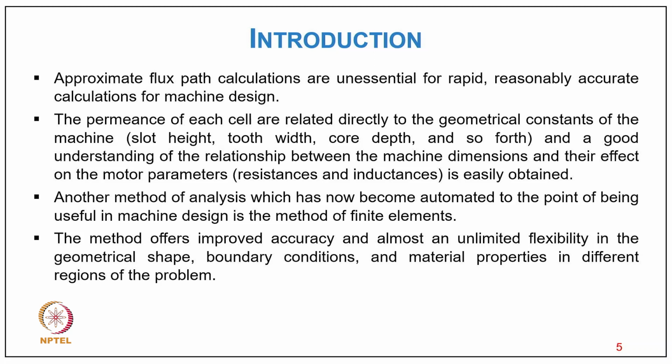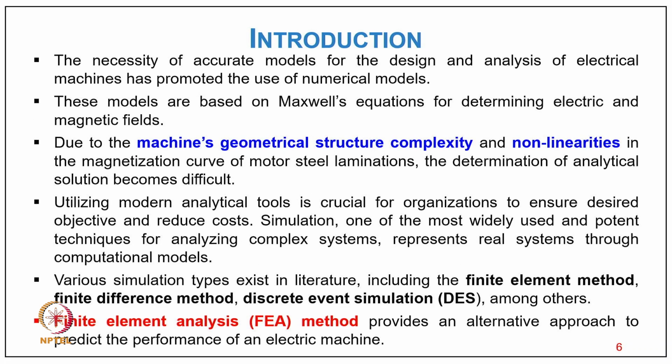The method offers improved accuracy and almost unlimited flexibility in the geometrical shape, boundary conditions, and material properties in different regions of the problem. So the necessity of accurate models for the design and analysis of electrical machines has promoted the use of numerical models, which are based on Maxwell equations for determining electrical and magnetic fields in electrical machines.